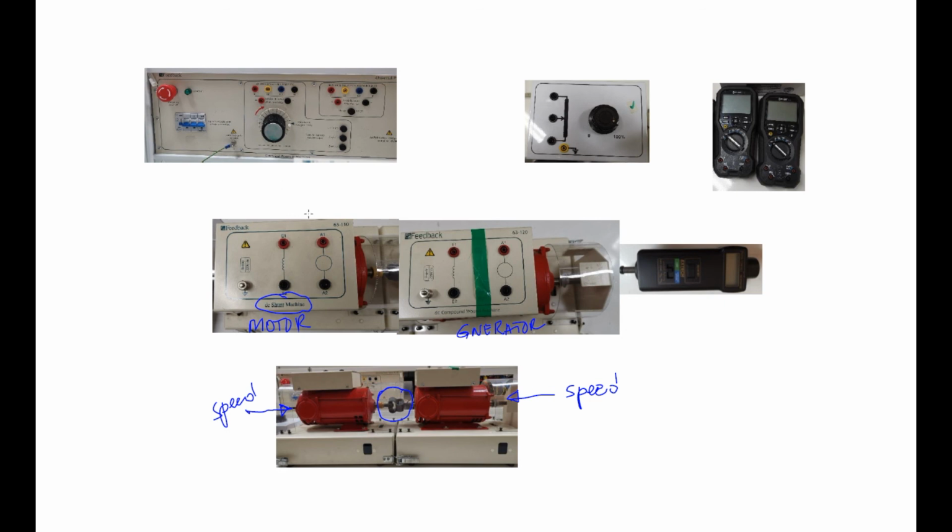As I told you, this is the motor, and first of all we have to make it a shunt motor. That means we have to make 2 jumpers, one up and one down. To make this clearer, maybe I can remove this one here. So this is our motor.